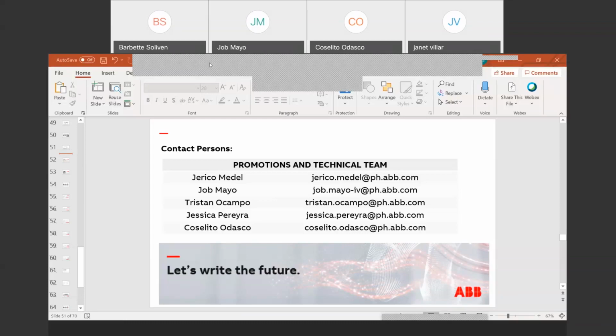Okay, thank you, Job. The next question is, in the Philippines, what is the standard used for testing low voltage circuit breakers? What tests are conducted for circuit breakers? So, the two questions, Job. Well, if you explore the Bureau of Philippine Standards, basically the standards governing consumer goods circuit breakers, it should be tested at 60947-2.